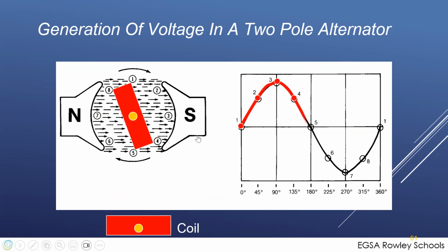As we go out of alignment, the voltage goes to 0, and then it comes the other direction as the other pole alignment comes up. I didn't put north and south on here, but conventionally a north aligning rotor with a south aligning stator produces the peak part of the voltage.